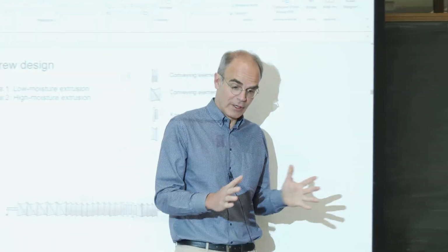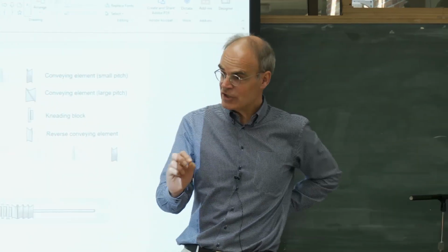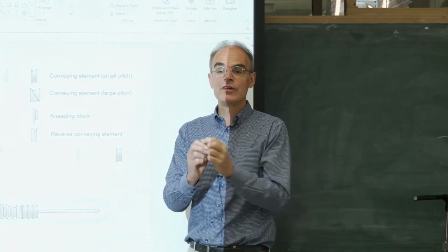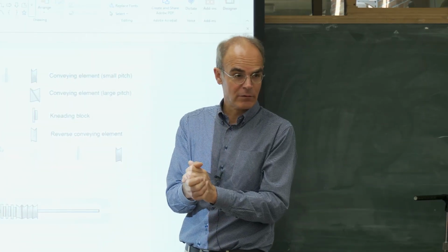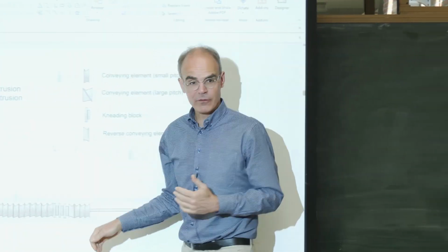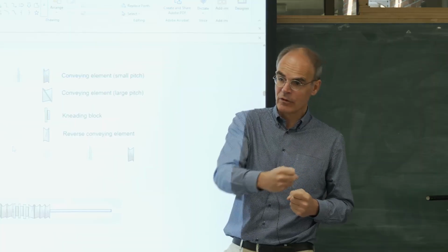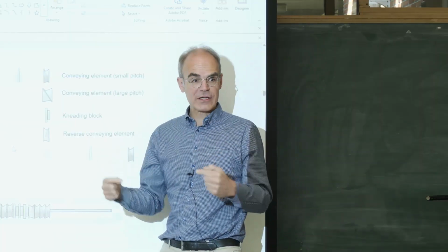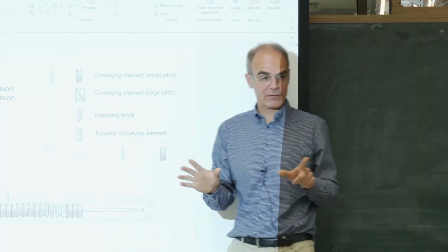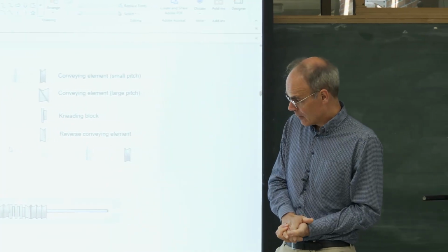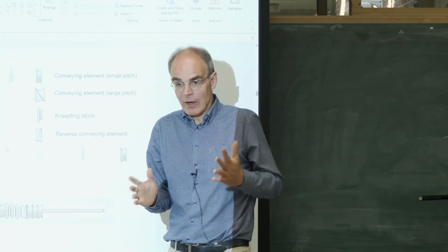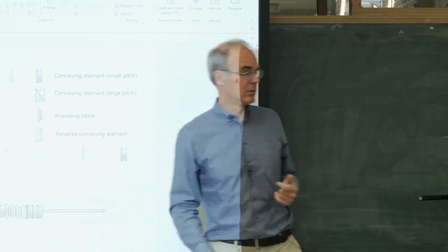So depending, and that's really where the key design decisions on your screw profile are: how much of those kneading blocks do I need? You make a balance between the forward movement of your material, the active transport, and the thermal effect, so the gelatinization and the denaturation or softening of respectively the starches and the proteins. But very often you'll decide you need more kneading zones.